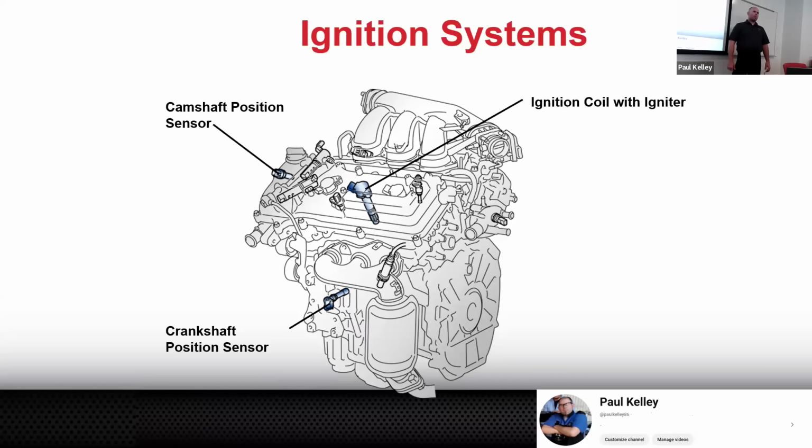Now, like I told you a week or so ago, the customer who called with the mobile mechanic story, if it's somebody like that, I'm kind of like, you know what? If all I do is give you advice over the phone, I won't bill you. Just switch the coils and see if it follows. I'm good with giving that advice. But if I'm going to physically do it, that's part of my diagnosis.